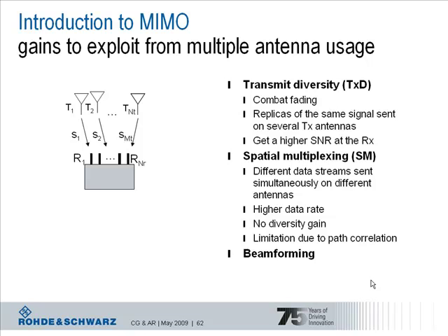The transmission may not always be successful, and this really largely depends on the correlation characteristics of the mobile radio channel. If the channels that are formed between the transmit and receive antennas are highly correlated, then the performance of spatial multiplexing will deteriorate. So spatial multiplexing really works best in uncorrelated scenarios.